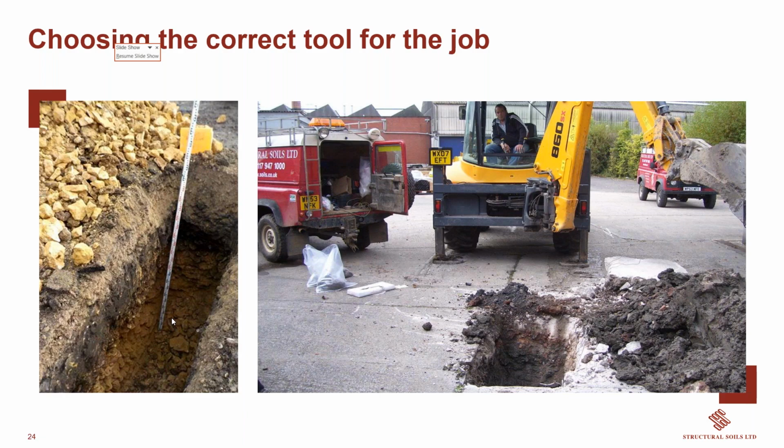We'd have to go away and come back with a trial pit, with a JCB 3CX on this. So again, it would cost money to come back to site. So we need to look at the geology and anticipate roughly what material we're going to be going through before we go to site.